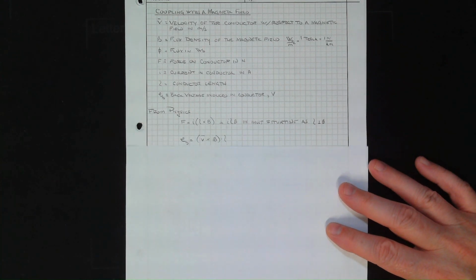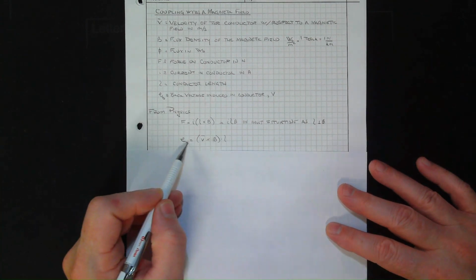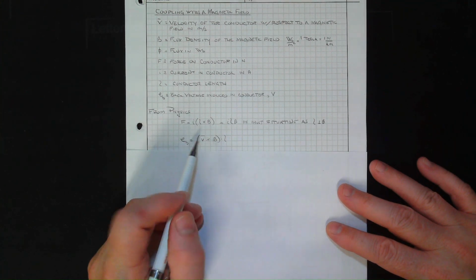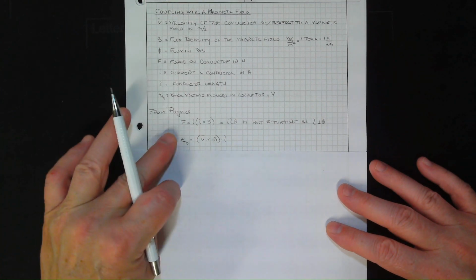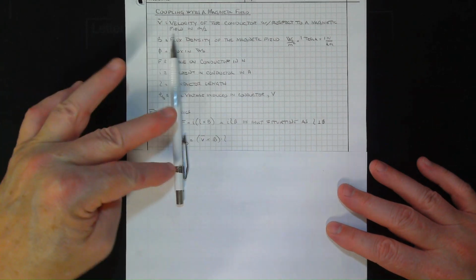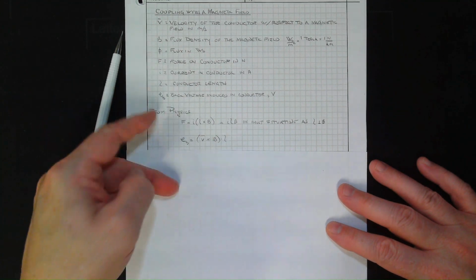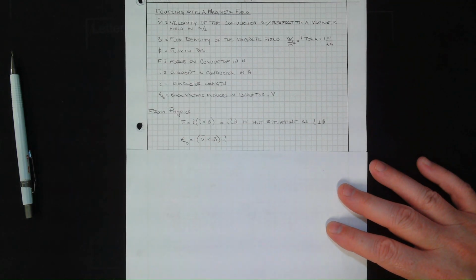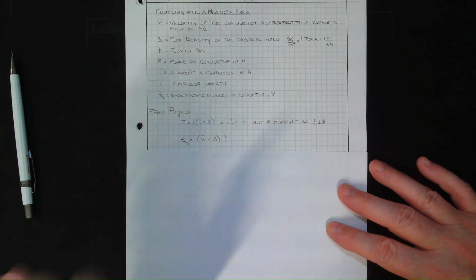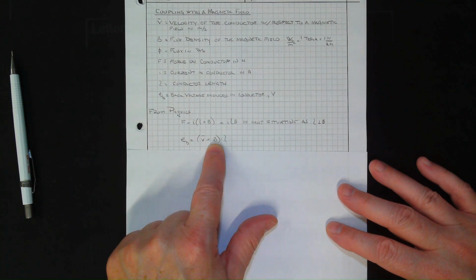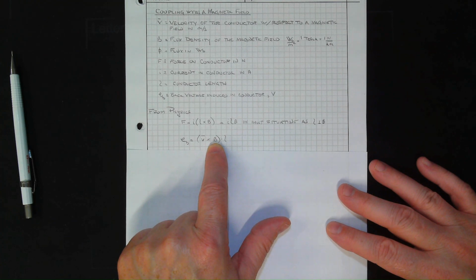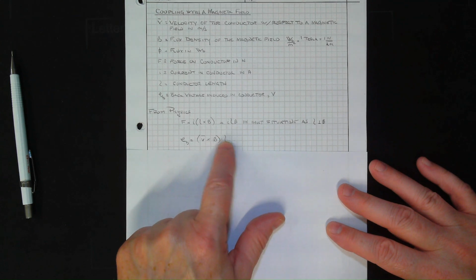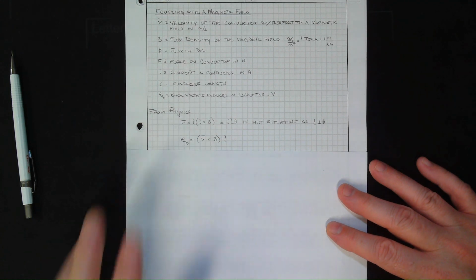All right. The other equation is the back voltage is equal to the velocity of the conductor through the field cross the magnetic field. And that basically sets up the plus-minus sense. Is it minus plus or plus minus for the voltage? That's not going to be a major concern for us actually. We have velocity cross the magnetic flux density, then times the length of conductor. So if you have lots and lots of conductor going through, you can build that number up.